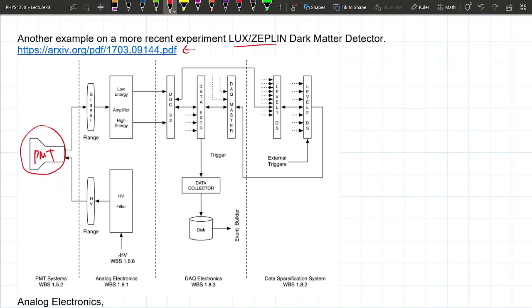For your photodiode, you need maybe 10 million photons to hit it for you to see the signal. Remember you did these calculations, right? This can detect a single photon instead. One photon hits it, you can see it. So if you have this on and you turn on the light, you actually break the thing. So just in case in the future someone asks you to turn on the lights while your PMT is on.